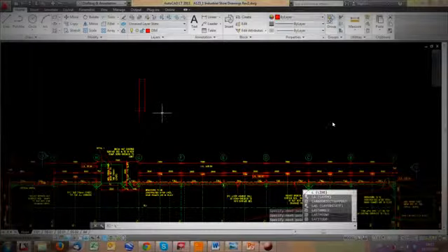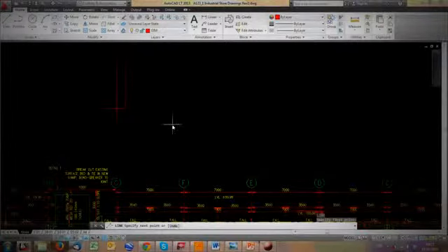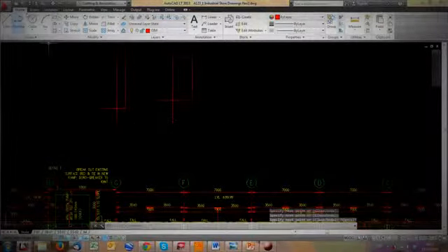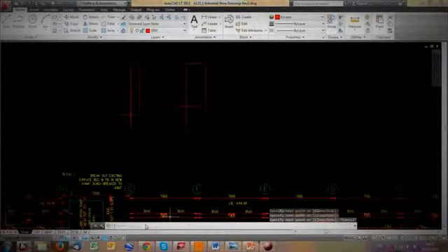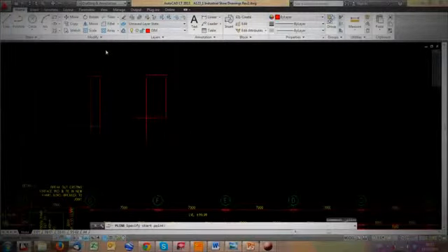If you look on the right, L, layer, etc. Type L for line, press enter. Now it starts a line command, and I can draw a line from the command prompt or the ribbons at the top. So that's different ways. And this command prompt is very useful. As you're drawing, it'll often give you options of what you draw.